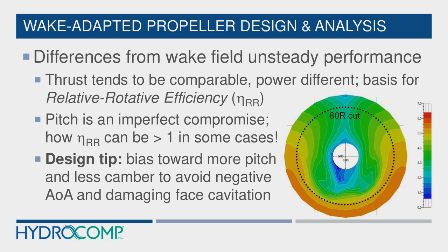What that means is that our average steady calculation really is a little bit of an off design compromise, and that by bringing some of that back into the lower two-thirds, where it's in faster velocities and more uniform, it's actually a little better than the compromise. We have to hit the thrust because that's what moves the ship. So that's where our thrust works out to be.